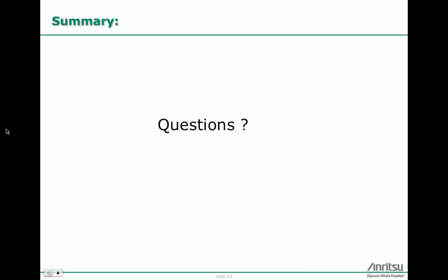And had a question on how are we getting IM3 out of the AWS band and the 700 megahertz band? Okay, if you think back to the slide where I said you have to use frequencies that are necessarily outside of your licensed spectrum, that's how we're doing it within the 700 megahertz band. So I think if you look at the upper block and the lower block, I think it is possible in the lower block of 700 megahertz. If I go to the very far extremes of the licensed spectrum, I think I can create an IM3 that falls within the receive band.